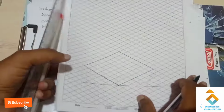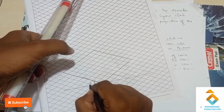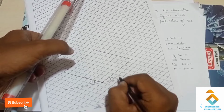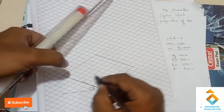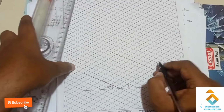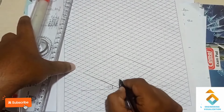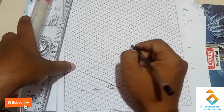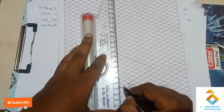Now we have to give the thickness for this box. You can see all these lines are at an angle of 30 degrees. Here the given thickness is 30, and 30 means 3 boxes. Thickness is nothing but the vertical height we have to consider. Mark 3 boxes here: 1, 2, 3. Draw the vertical lines here.